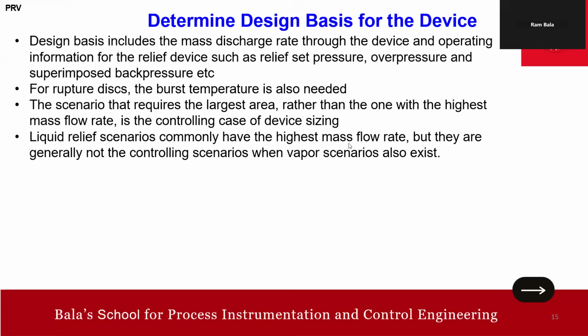That is important. Liquid relief scenarios commonly have the highest mass flow rate, but they are generally not the controlling scenario when vapor scenarios also exist. That is also something we need to take note of. So these are the determined design basis.